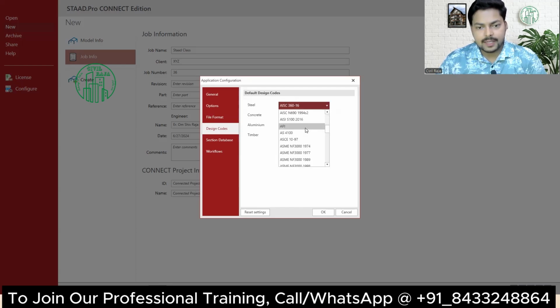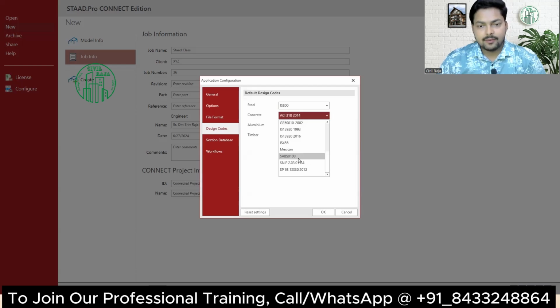For steel, I always have to use the steel code as IS 800, so I will simply choose IS 800. Then you also have options like IS 800 2007 for LSD, a limit state method, and for the working stress method you also have the option, but I need IS 800, so I will simply keep it like that. Then for this one I will use IS 456 for our concrete. We all know that concrete is IS 456. Aluminum we do not use, the timber we do not use, so you can simply keep it like that. Okay, that is not an issue. We can simply keep all this as default.